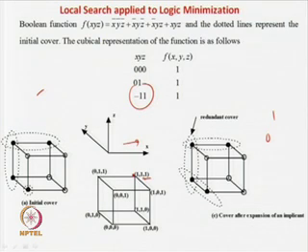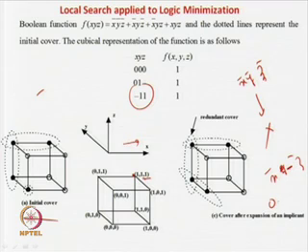Now, you can see that this is your initial cover. Our idea was that we have to try to remove some of the literals from the function and see if it still works or not. So if you look at this function, it is x prime, y prime, z prime. Let me try to remove a literal from this one. If I remove, say, the literal y prime, then what is it going to become? It will become x prime, dash, z prime, that is 0 dash 0. What does it correspond to? It will correspond to these two terms. This one was 0 0 0, and if I eliminate this, it will become something like this.